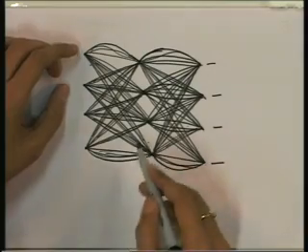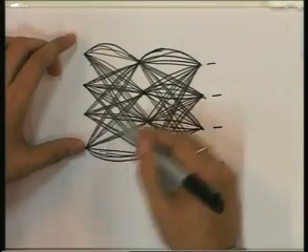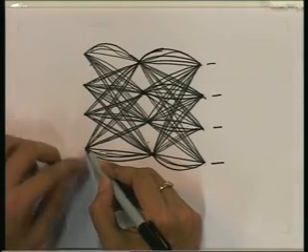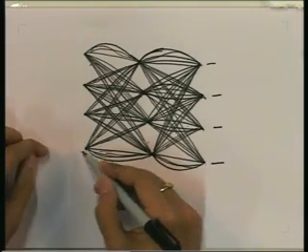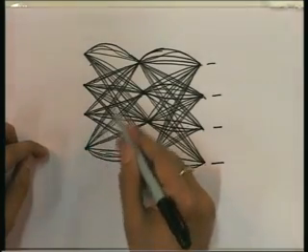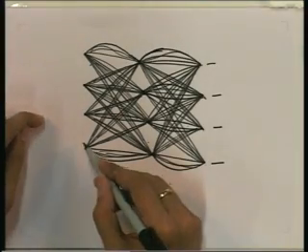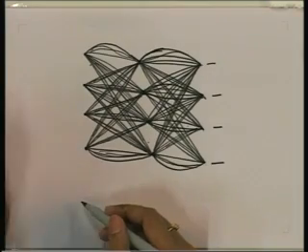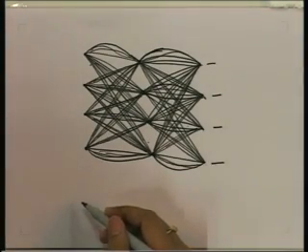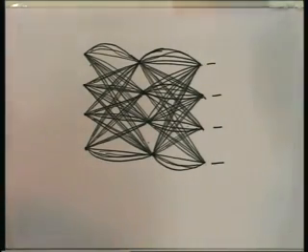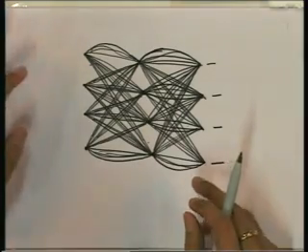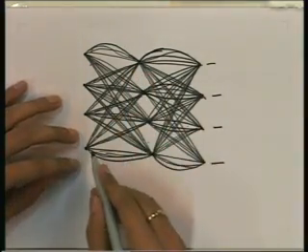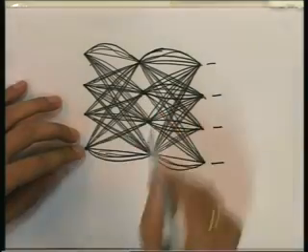And again just like binary, we will have many lines for each transition, because if the previous symbol was also at this level, it will take a different path here. If it came from a different level here, it will go again in a different way, and so on. So, for binary there will be few, and for PAM also similarly there will be many lines from any level to any level in the next interval.